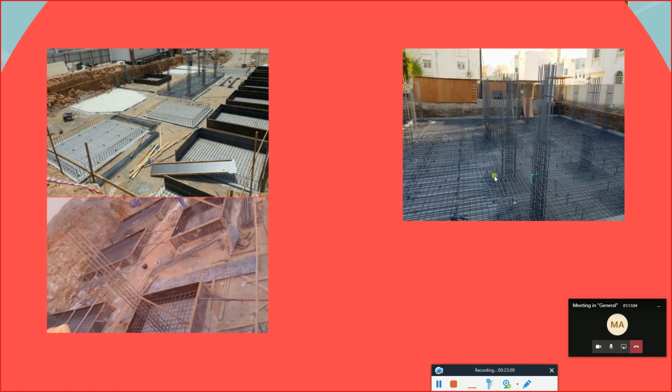Now after having the formwork, there is another picture which is representing a raft foundation here. So this is an isolated system. Here it's a raft foundation system, and once again you can see the covers inside as well. After the reinforcement, once again we are showing the formwork. We are extending our column. This is a foundation column.